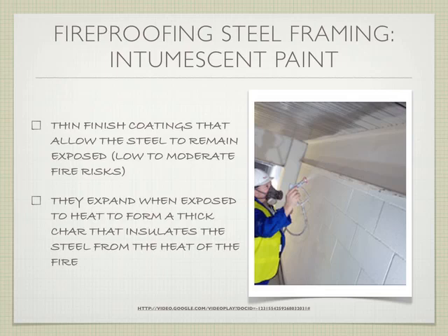The key one that's used today in practice is something called intumescent paint. And it's a really cool substance. It goes on just like normal paint. It's a little bit thicker than normal paint. It looks like normal paint. You can color it like normal paint. You can paint over it with a different choice of paint. But when it's exposed to fire, it expands and foams up,